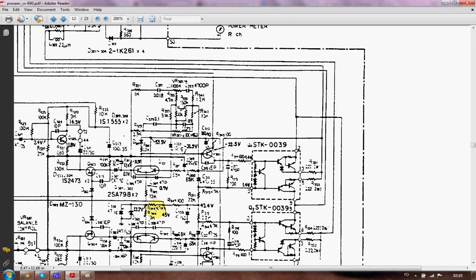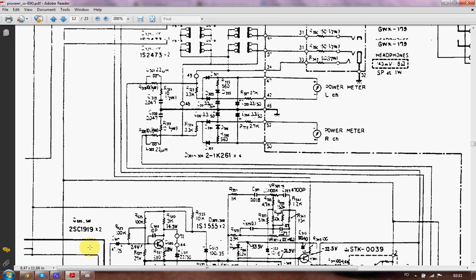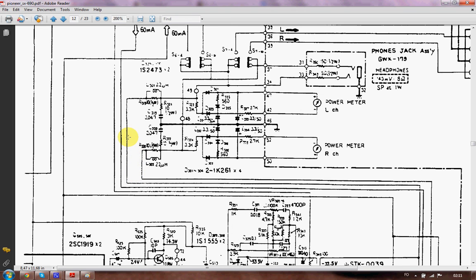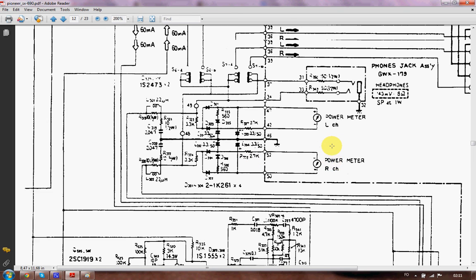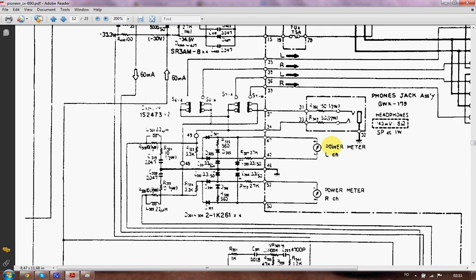Where in the circuit does the wave disappear with the oscilloscope? And where in the circuit does the voltage disappear? Where is the break? Where is the faulty component? Or where has a wire broken, or a soldering joint blown? And as I said, try to do the easiest things first. Clean the contacts, check the fuses, have a visual inspection.